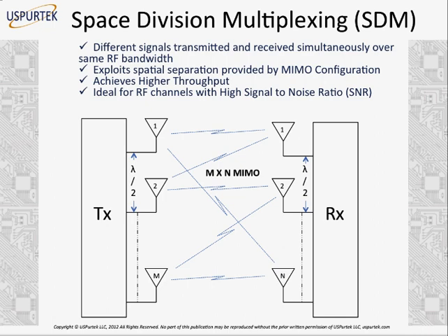Remember, MIMO does not need more bandwidth or more power from the transmitter. It simply uses additional space which is freely available. So SDM does not exhaust the frequency resource, but uses space as a resource by exploiting different directional beams that can be sent from an antenna array.